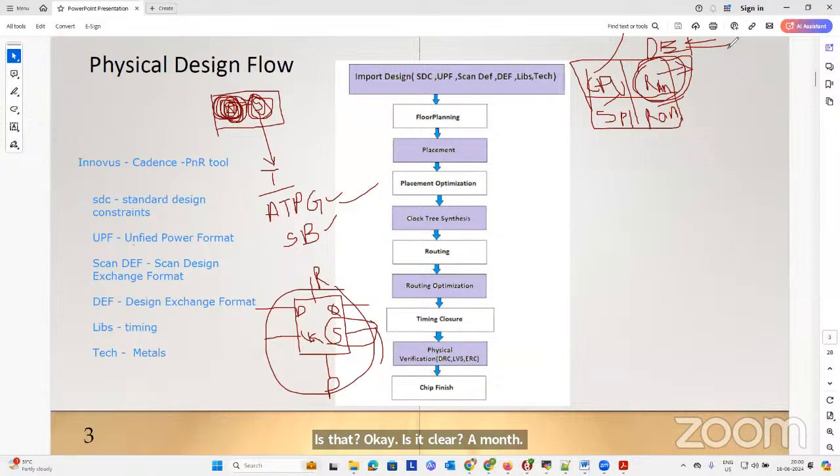And at each and every step of our design, we can save our design files in def format, which is a database file format, where we can import, export, or reuse these files in cross-platform tools, from Cadence to Mentor Graphics to Synopsys, or any other cross-platform tools. Only for that they are called design exchange format files. Clear so far, everyone?